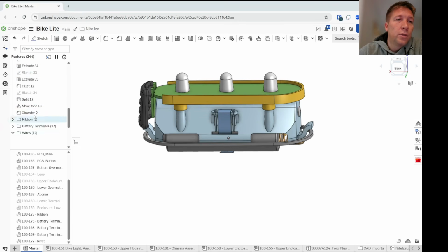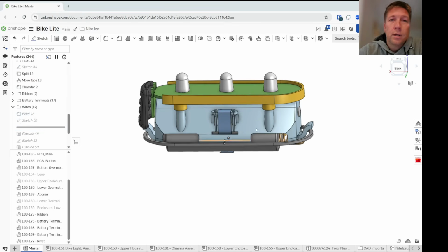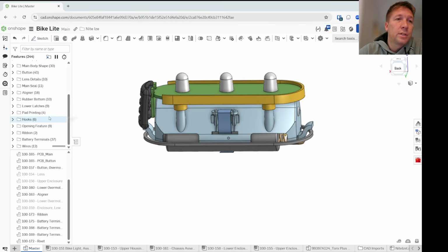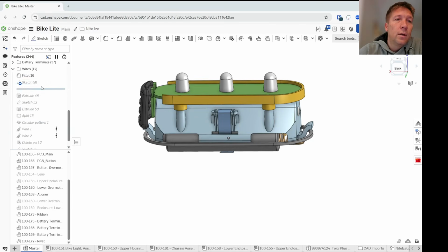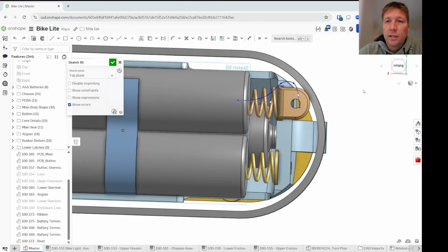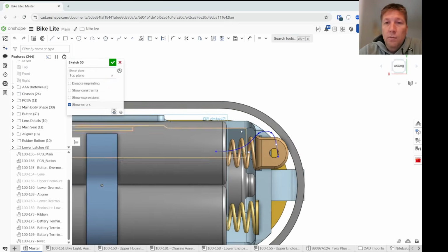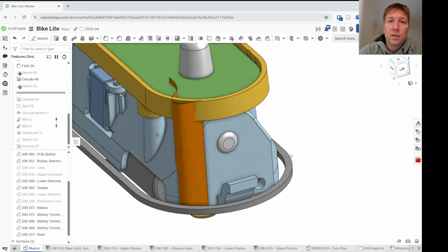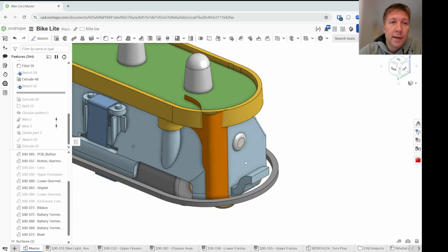So to build the wires, I needed to create a line or a 3-dimensional sketch curve. So what I did is I created first a spline curve that goes in one direction, from this line to here. And I kind of had to play around with this curve. I haven't actually even fully defined it yet because I might move it. I don't know. But that's one sketch. Then I created an extrude from that sketch, which is just a surface. And so where that surface goes is where the wire edge is going to go.